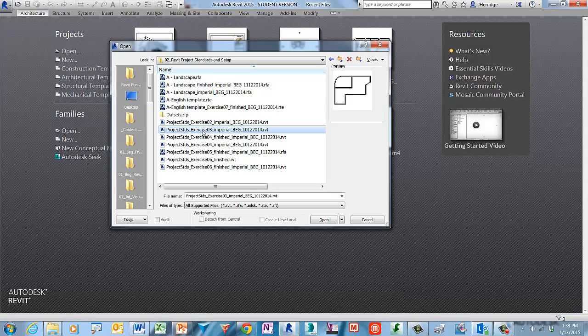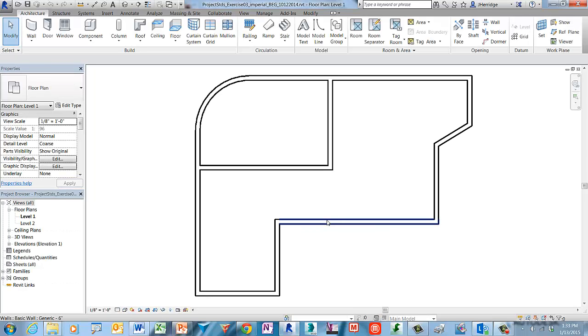In Revit, there are two types of dimensions, temporary and permanent. Temporary dimensions display when you select, create, or insert components. Permanent dimensions are created explicitly by the user to capture design intent. This exercise shows how to define different permanent dimension styles based on the appearance of the dimension text and lines. Each dimension style automatically adjusts for different view scales.